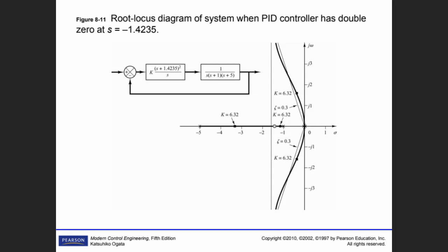This is the root locus curve, and this is the second Ziegler-Nichols method. In the first attempt, we calculated Kp, Ti, Td, and we employed that and drew that curve. Are you happy with that curve? No. Since we already got the step response, and it was very bad. It was 60%.